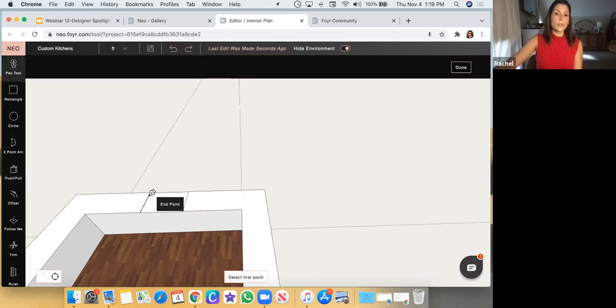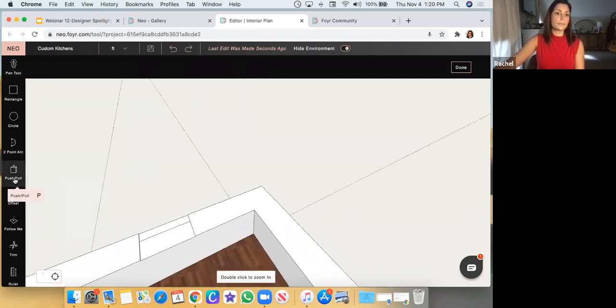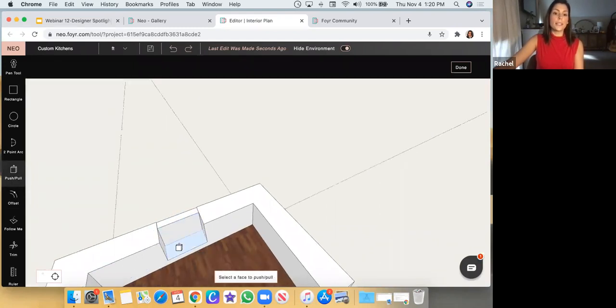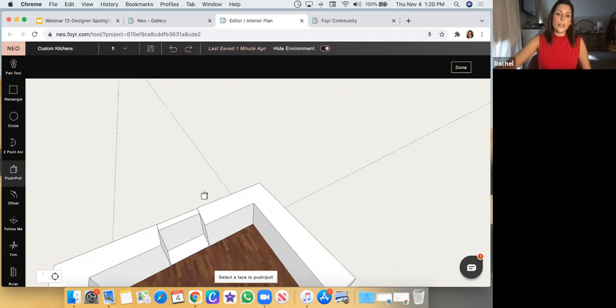And then you would just use the pen tool to draw here and define it as a separate plane so that you can just push this down. That way you have a space for your faucet to sit in the back without having to use a wall docked cube to create that additional space. You could always do that if you sliced it away and didn't have it to work with, or you couldn't undo because maybe you were working on other things. You can always just use a wall docked cube to create this little backing, but you can do that here as well.